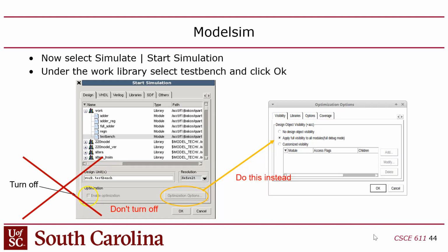And then when you want to start the simulation, you can actually just type vsim inside the command line window with the top level module as the argument. So vsim space CPU, right? Or vsim space testbench. Or you could do it through the GUI. This is the way the GUI is set up. You just go to simulation, start simulation.